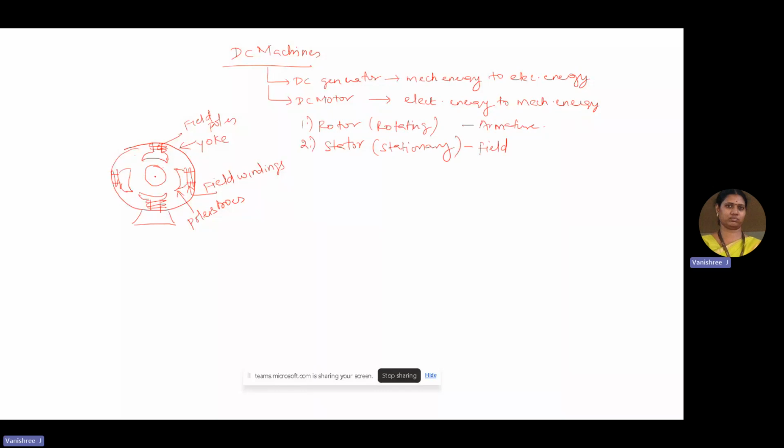Here, the armature which is present in the middle will be having a shaft and it has the armature slots in it. Armature slots are necessary for incorporating the armature conductors into it. Armature is the housing of conductors. So don't imagine when I say the term conductor that the conductor is a solid conductor. Conductor is again a wire which is wound in a separate fashion.